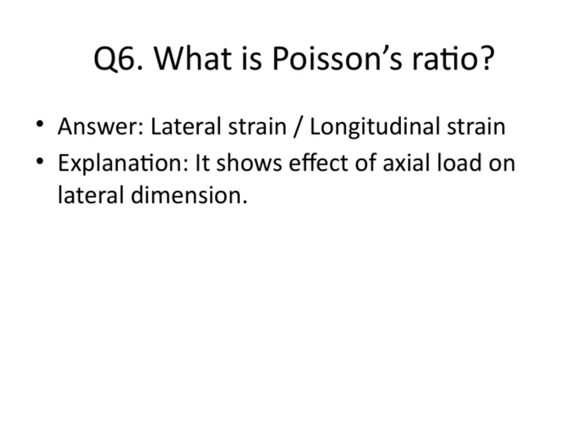Understanding Poisson's ratio helps us predict how materials will behave under various load conditions, which is crucial in designing structures and components that are both strong and reliable. So, in essence, by examining how a material responds laterally when subjected to axial loads, and knowing Poisson's ratio, we gain important insights into the material's overall elastic behavior. This fits into our broader goal of understanding material mechanics and ensuring safety and durability in engineering applications.